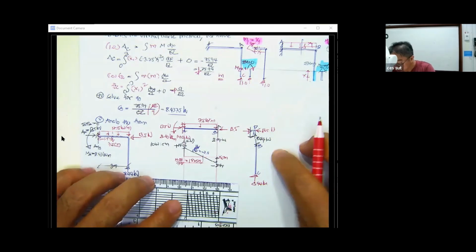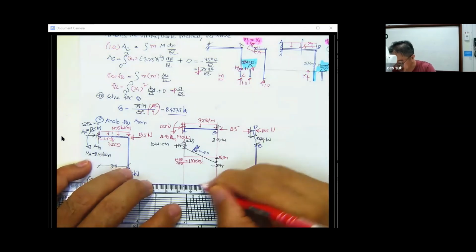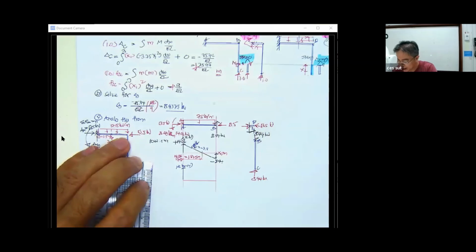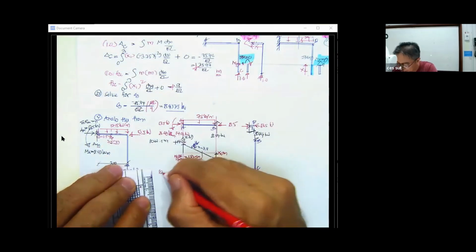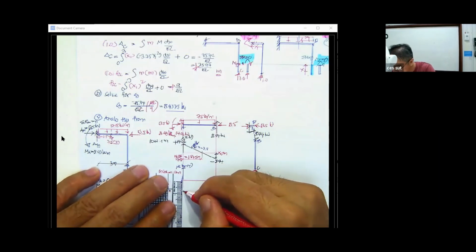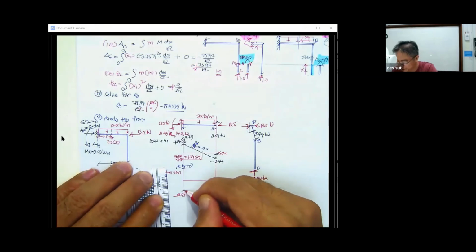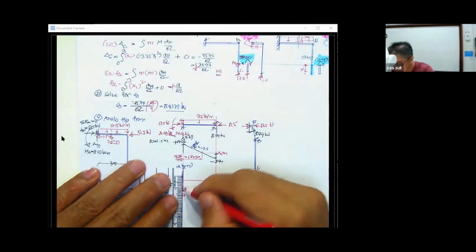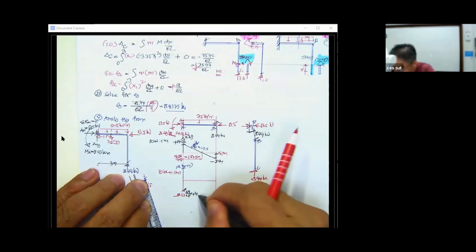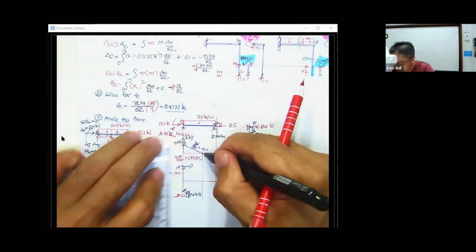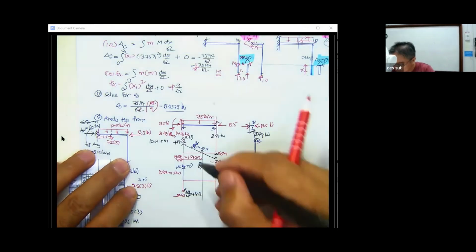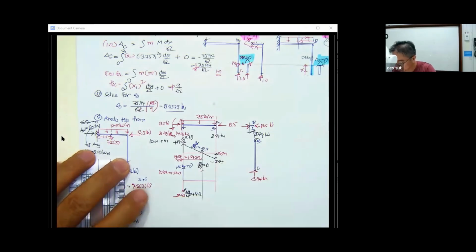And then we have the moment diagram, and we set this up as the moment in kilonewton meter, and we have 8.43. Set 10 kilonewton meter per 10 millimeter. This is 8.43, so it's going to be 8 point something. This one is minus 8.43 over here. And then the slope here of 14: dM by dx is going to be plus 14.06, and over here shear equals 0. So dM by dx is equal to shear 0. So the maximum moment is supposed to be here.